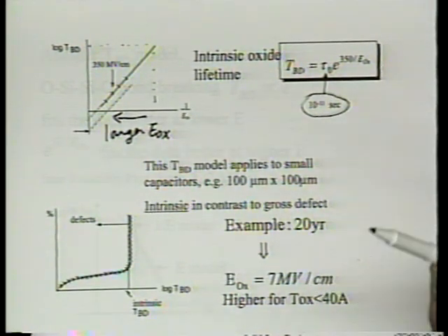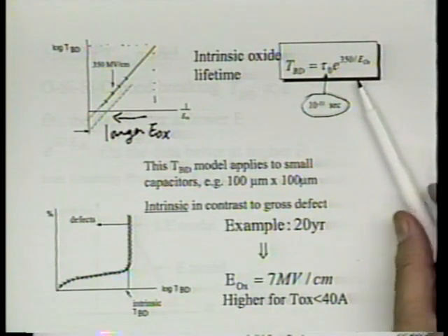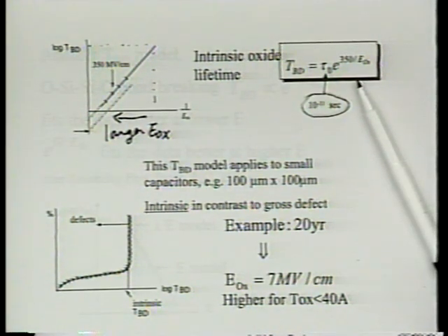So if you use this equation, if you accept this, now it's a very powerful model because there's no unknown at all. A problem that used to be very complicated, remember, last hour I introduced this oxide modeling problem by reviewing for you that through the last several decades, there have been many predictions of MOSFET scaling where it ends at half micron, ends at 0.2 micron, ends at 0.1 micron, and so on and so forth. And I argued that the reason people didn't know where it would end is that people did not know oxide breakdown capability. Turns out that's what it is.